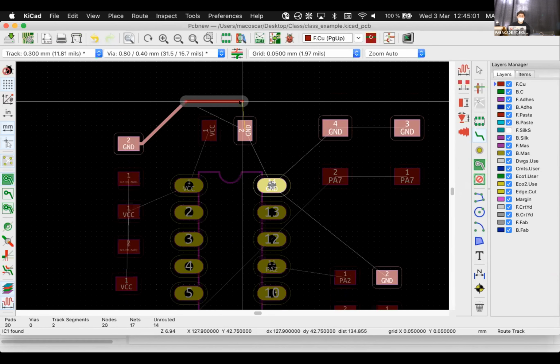And that's good, okay? With these wires at the beginning, I recommend that you try and iterate. You're not going to get it the right way on the first try. So this comes with time, be patient and gain experience. It will be a little difficult at the beginning, but you will get better at it, okay? What happens if you messed up? You can put the mouse over the track and then delete with the backspace. Or again, right click, delete. Okay? Good?